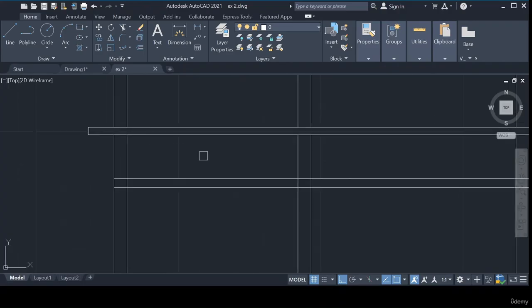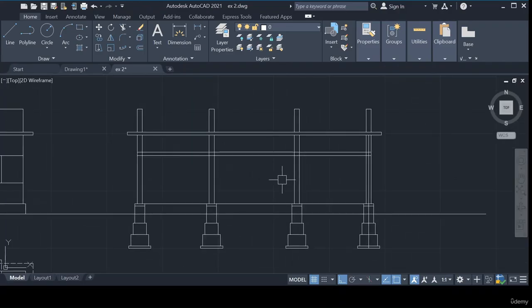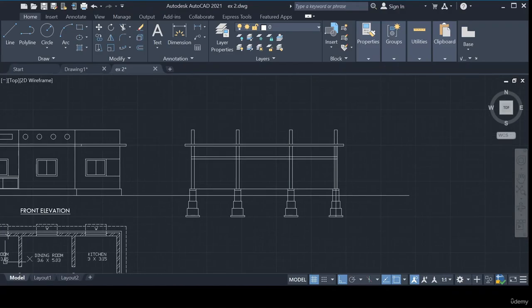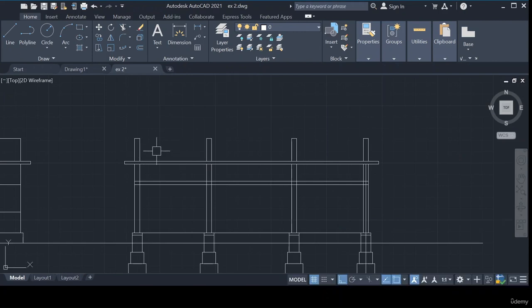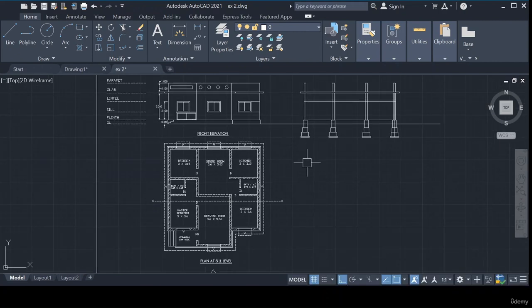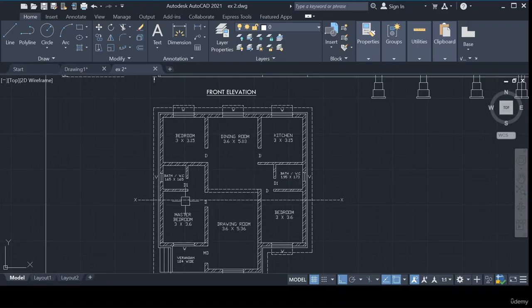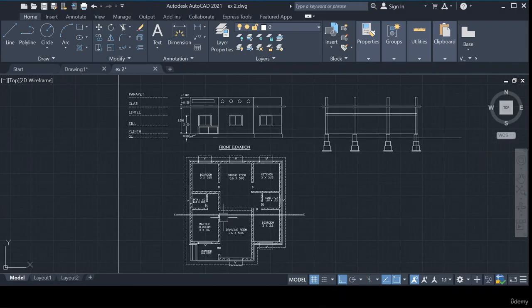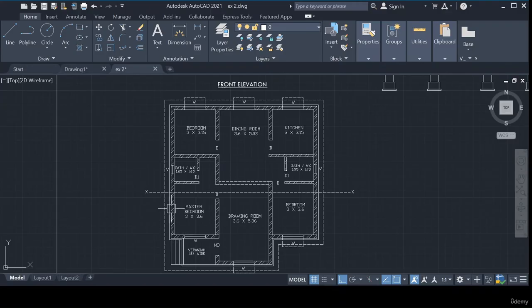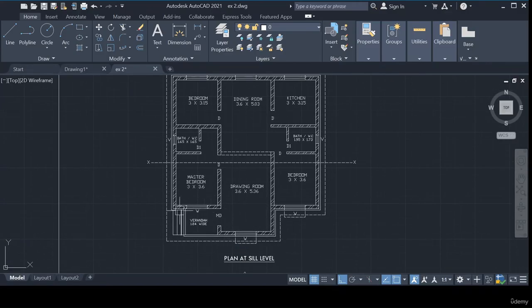And here one more thing, the parapet. So here this is the parapet, this is the parapet. Always remember, here it is cutting, this is the inner wall, this is the exterior wall. Corner walls are the exterior walls, and middle walls are interior walls. The parapet we always provide at the exterior walls only, not in the interior walls.